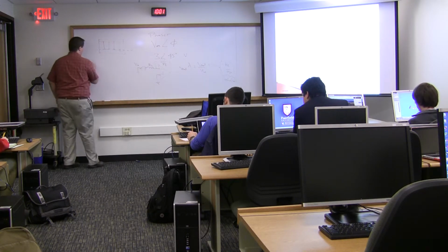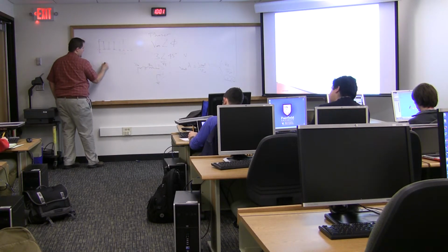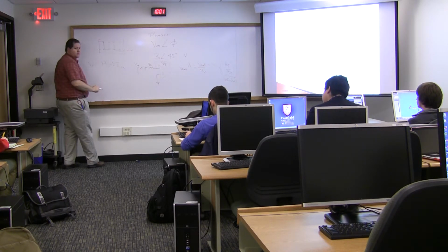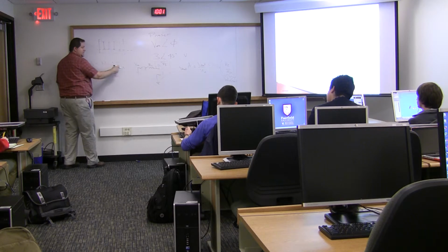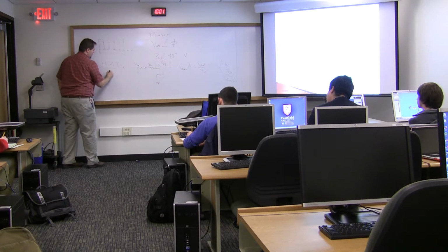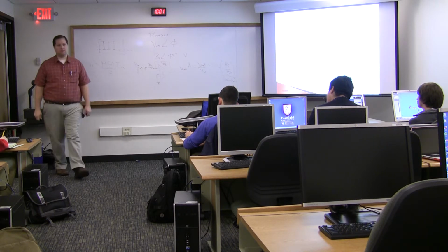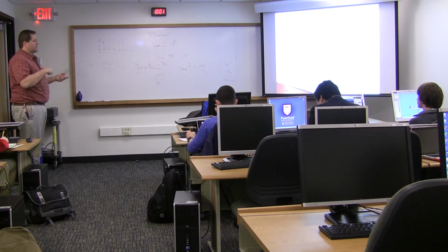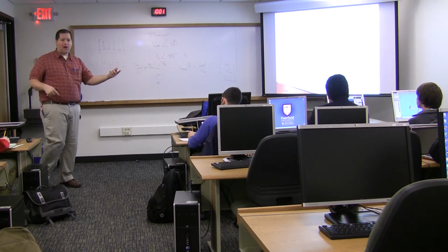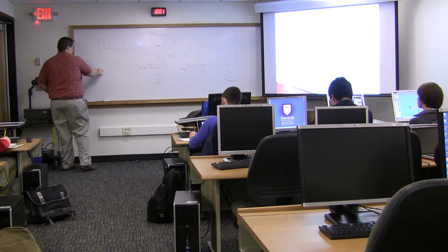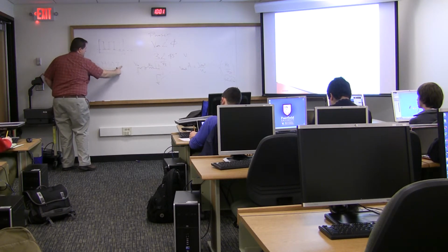So if I look at my output VO, and it looks like H of omega times I in, V equals Z times I. So the H right here looks like an impedance Z, and we call that a transfer impedance. The opposite case of a voltage in and a current out, we call a transfer admittance. Just move this to the other side, change the subscripts.